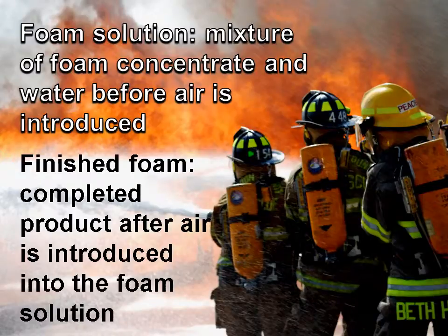Your finished foam is the completed product after air is introduced into the foam solution. So you have the foam concentrate, which is just the foam itself, and then the foam solution is the water and foam mixture, and then the finished product is the foam when the air is introduced. That makes your foam blanket. That's where you get the bubbles from, is from your air.